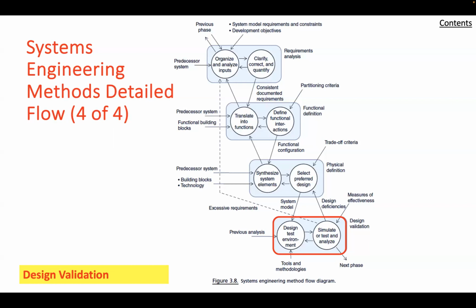In carrying out the above process, it is most important to observe the following key principles. 1, all critical system characteristics need to be stressed beyond their specified limit to uncover incipient weak spots. 2, all key elements need to be instrumented to permit location of the exact sources of deviation in behavior. The instruments must significantly exceed the test article in precision and reliability.